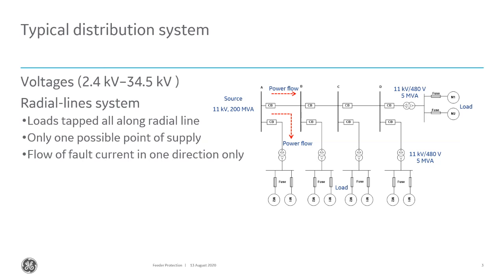The basic purpose of the circuit breaker, the auto recloser, and the fuse that we'll talk about is to interrupt or isolate parts of the distribution system when there is an abnormal operating condition in the distribution system. There are a number of different abnormal operating conditions they can operate off, but the most common that we think about is short circuits, right? Whether it's a phase-to-ground fault, three-phase fault, or phase-to-phase fault.